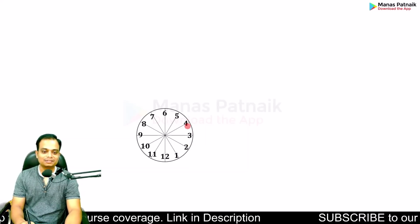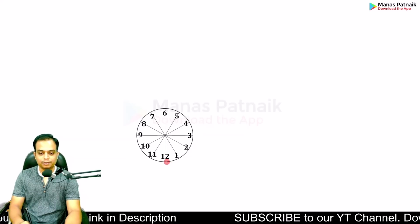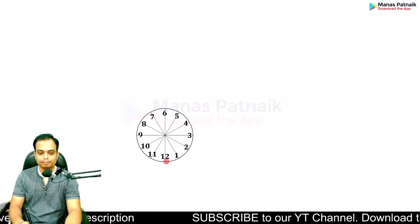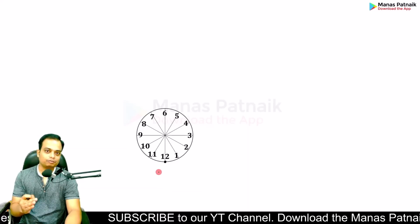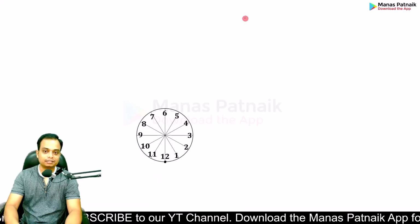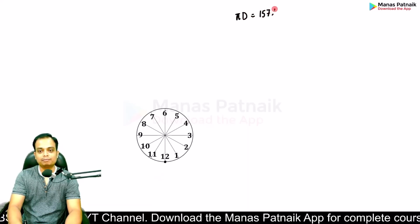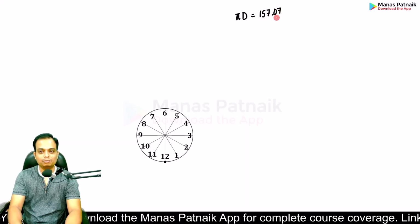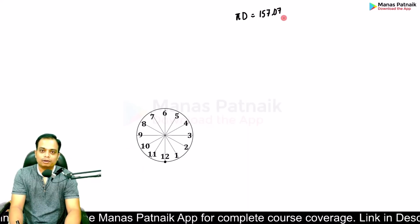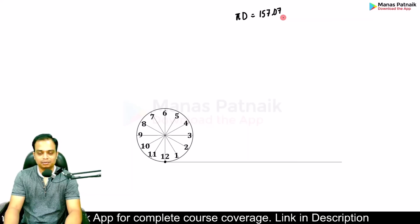All right, now what we'll do is we'll simply draw a line from over here, from this very point. The length of the line is equal to circle's circumference, that is pi d, which worked out as 157.07. So make it as 157. You won't be able to mark 0.07 or go for 157.1, right? That's the best we can do.